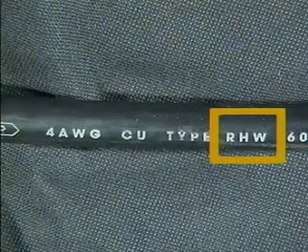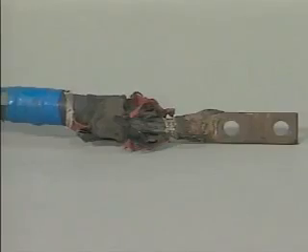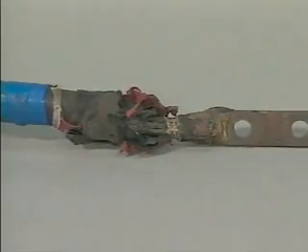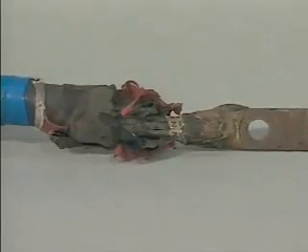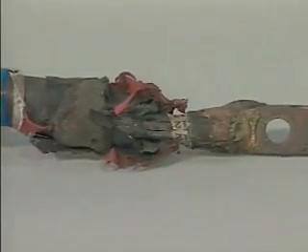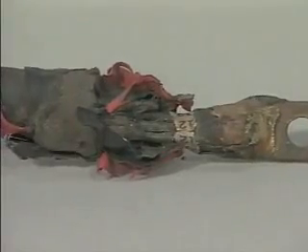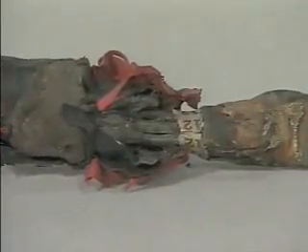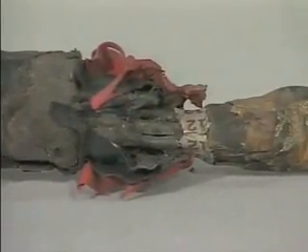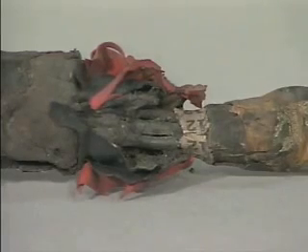Exceeding a conductor's allowable ampacity will cause the insulation to overheat and fail. This can cause personal injury or equipment damage. So it's important for a conductor's allowable ampacity to be equal to or greater than the amount of current in the circuit you're going to install it in.